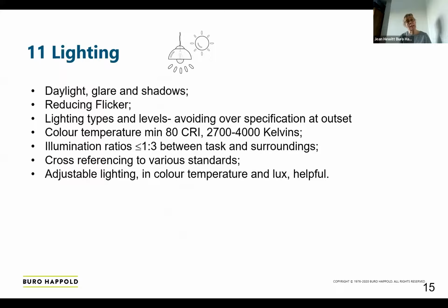And then on the lighting, that was another big area. So I would say acoustics and lighting are the two biggest areas. So the issues of daylight, yes, we love it, but you can have too much of it when it causes glare or deep shadows. How we reduce flicker. We knocked down a few myths about lighting types, because to date people said, oh, take the fluorescent lighting out and put LED lighting in, but it's not quite as straightforward as that, because LED can have a flicker too if you're not careful. So it's talking about the designer lighting.